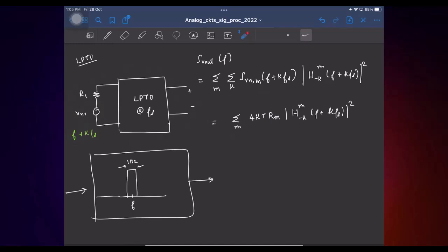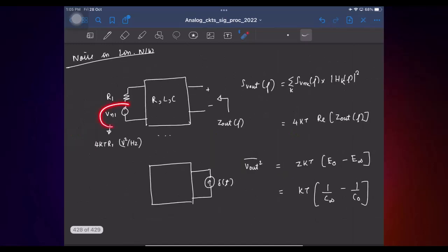And with LTI networks, such a stationary random process is processed by an LTI filter. Remember, an LTI filter is just imparting different gains at different frequencies, and the gain it imparts to a particular frequency is not changing with time. It's just some H(f).